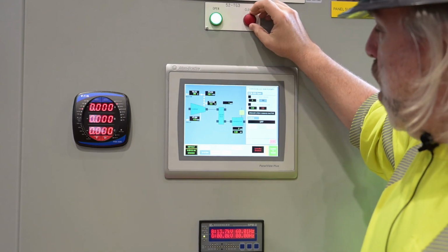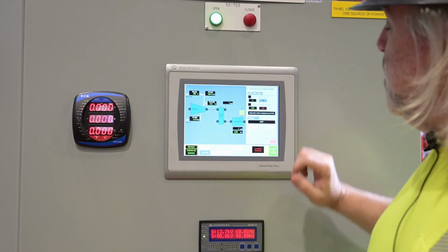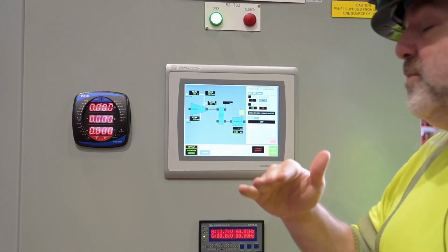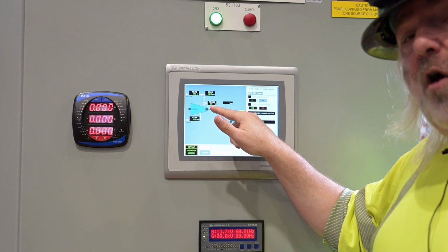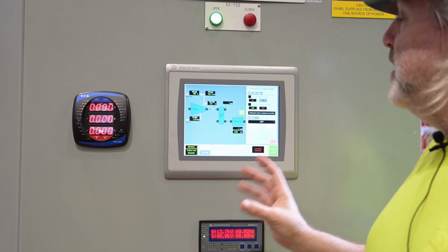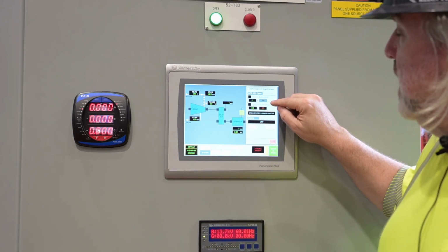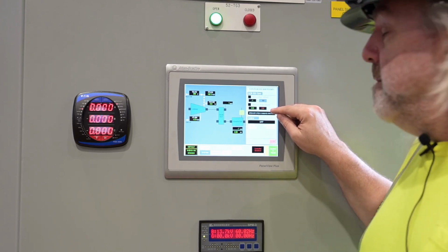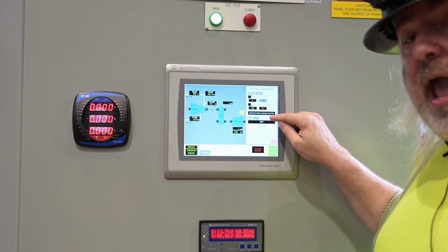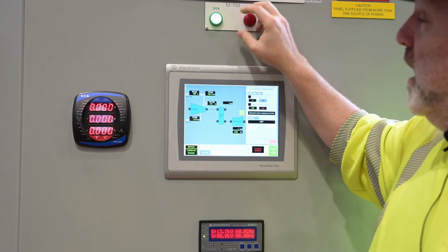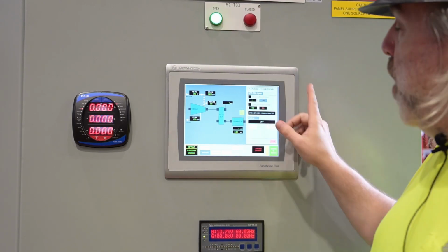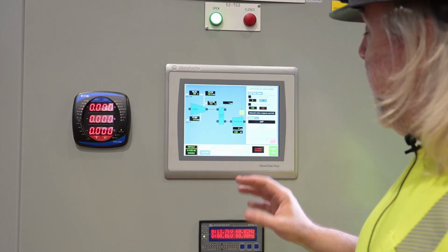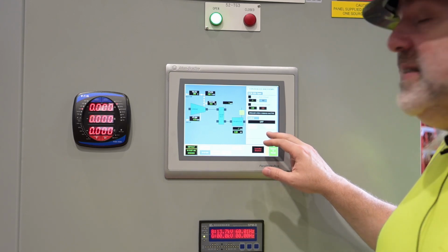If the breaker is closed, red, then when you enable the controlled shutdown, it'll ramp your control valve closed at a designated rate. Once you have achieved less than 50 kW and your valve is less than unload, then you'll issue a breaker open command. Once the breaker opens, goes from red to green, we'll be back into the speed set point ramp rate. Again, you can cancel this shutdown at any time.